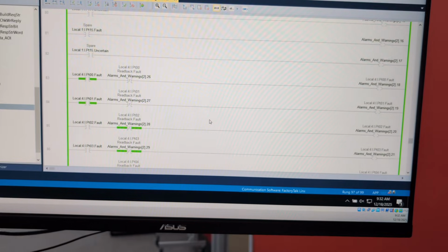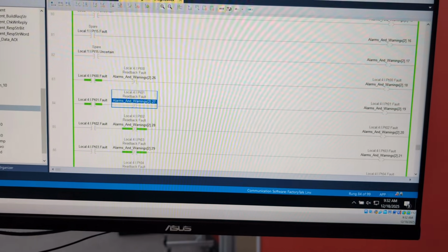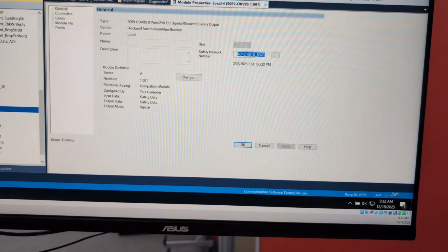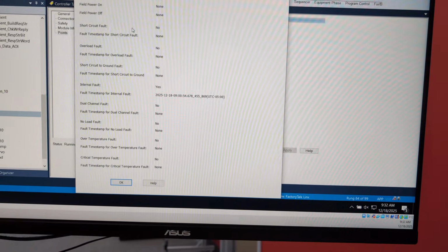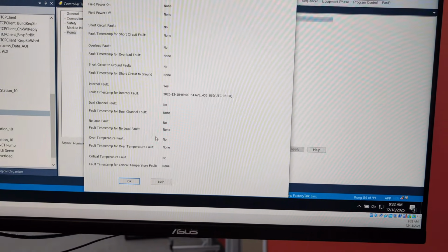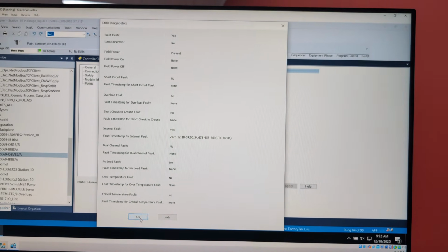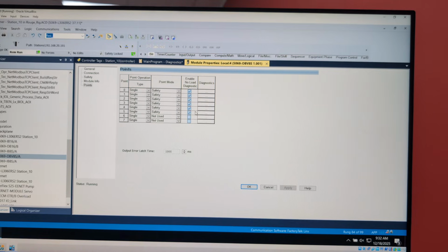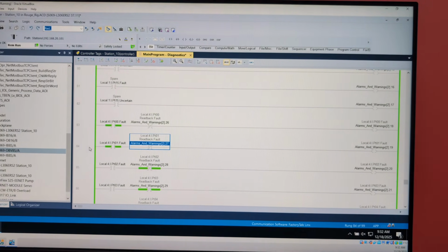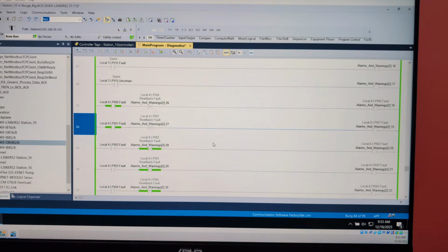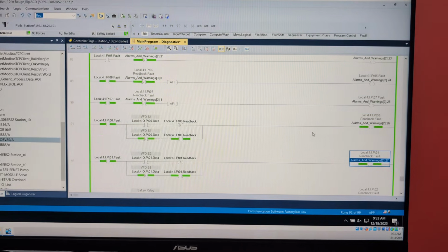But now we don't have that alarm. Now I gotta admit, I had a couple thoughts on my mind. One, they're still getting a little more info over here, so I'm wondering if there isn't a GSV that maybe has some better data. That might be something to dig into at some point. But also, if there isn't, I would probably eventually can this into some type of add-on instruction. But now we have 2 singular alarms. So we're only halfway there though.